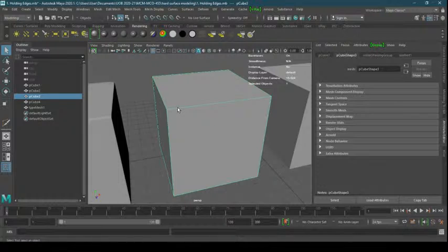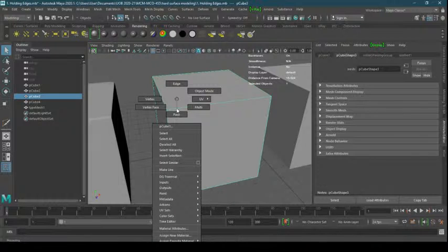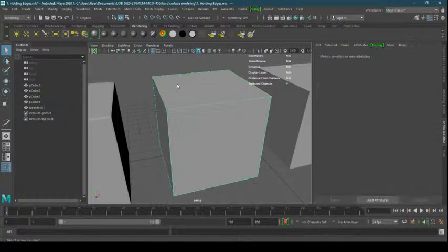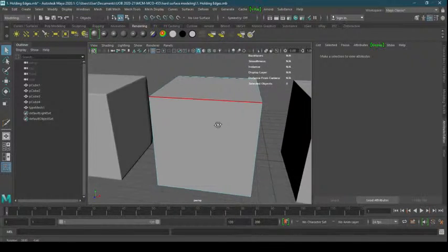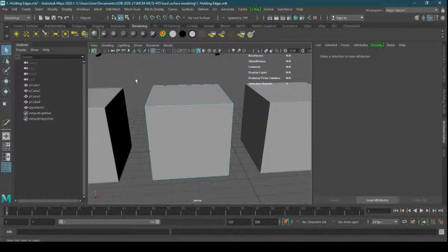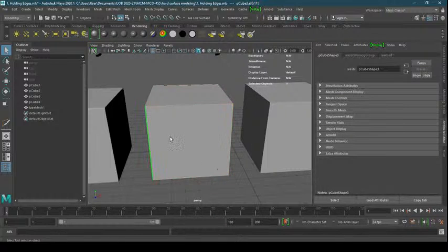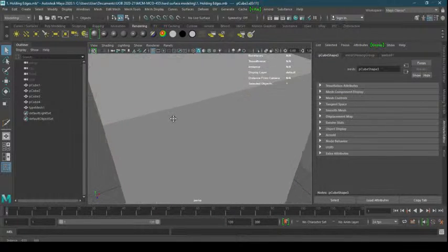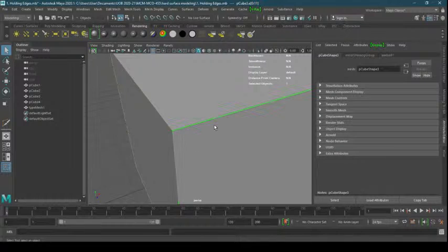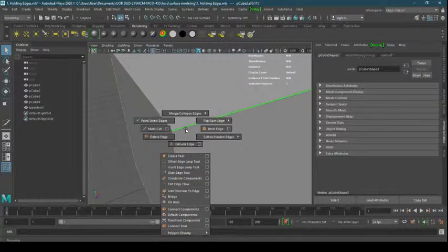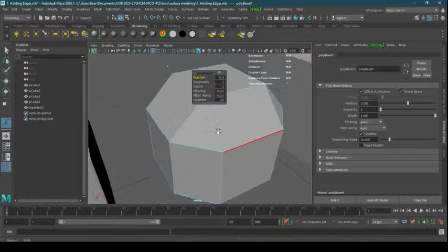You just right click on your scene without pressing any key and select the edge. So your edge will be activated. Now I will select all the edges just like this. All the edges are now turned this orangish color. Okay. Now what I can do, I can press Shift key on my keyboard, right click on these edges again. All of them are selected, so the effect will be on all of them all together. Right click, bevel. Now it will start beveling.